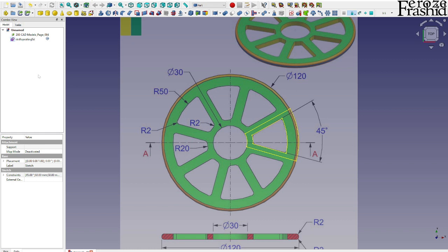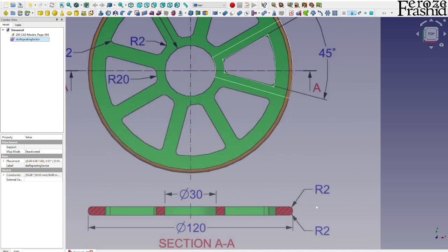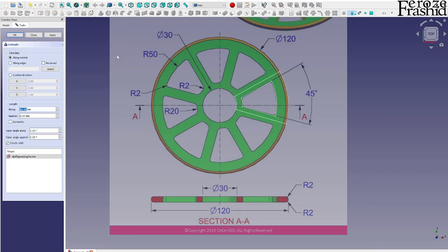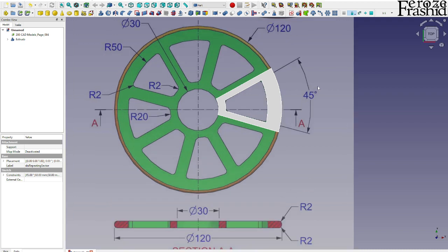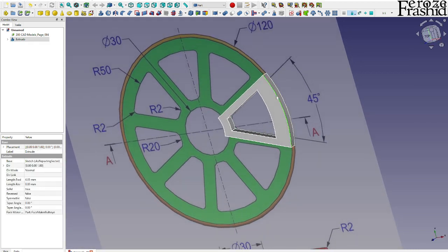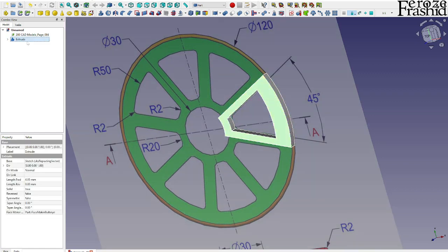All right, so that's our repeating, I'm gonna say, sector, and I want to pull it up for, so this is 2 millimeter and this is 2 millimeter, and so that would be like a 4 millimeter extrusion. So I'm gonna go ahead and make it 4.05. I just gave that 0.5 millimeter, just a little bit of wiggle room. Actually what I want to do is I want to make that extrusion symmetric to the plane.